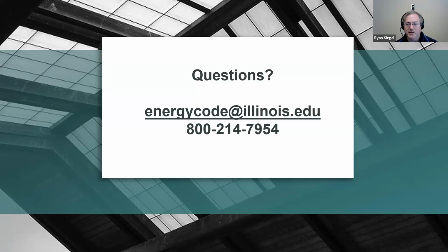And recognizing that the sunroom may also contain, in a porch application, depending on your design, not only walls but the ceiling and floor to contend with too. So just by enclosing a porch and making it a sunroom, if you don't add any conditioning, there's no specific requirements as far as those walls or anything. They don't have to meet insulation requirements if it's still remaining an unconditioned area from your unit.